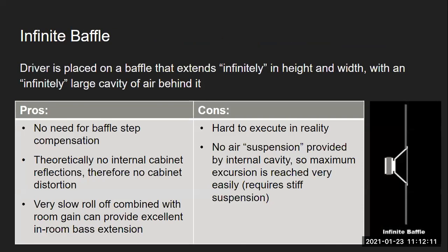And then we'll talk about the infinite baffle. This is an interesting one, mainly because it's probably most used in measurements, actually. A common way of measuring what a transducer is doing is you can drop it into an infinite baffle, which would be like cutting a hole in the wall and sticking a speaker driver in it. So it's a theoretically infinite baffle that separates a theoretically infinite volume on the back from whatever the listening environment is on the front.